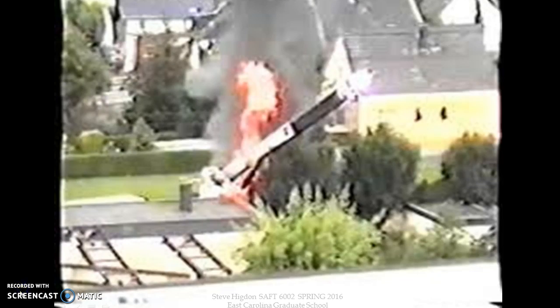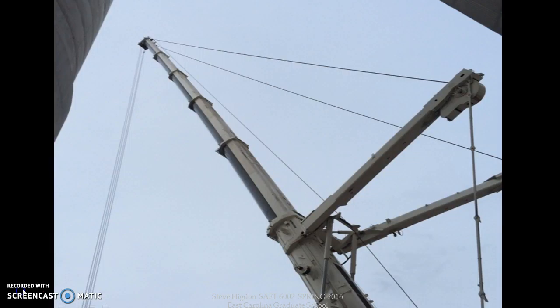After the crane has been set up properly, it is very important that you know the surroundings of the crane. One of the most important things you should look for is to make sure the crane will not come into contact with any electrical power lines. This is an extremely dangerous part of any critical lift. Also very important is to determine what is known as the swing radius.